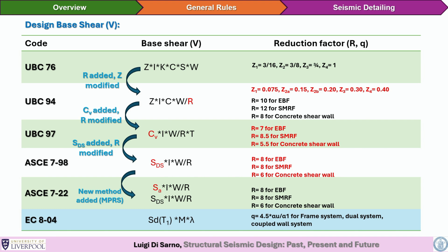the R factor, which is what I call to my students the discount factor, because really you are lowering down the forces, but at an expense, and the expense is the ductility. So you are not getting a discount without then paying off, for example, with your card in the supermarket. The same thing happens here. You get lower forces, but then you need to implement more seismic details. That's what we do currently in the so-called capacity design methods.